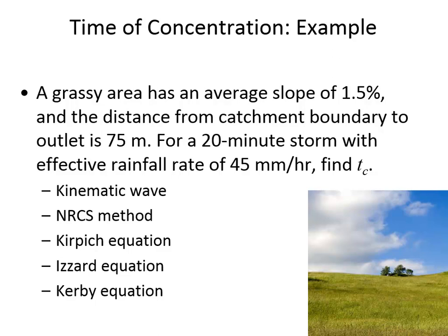And the problem with the Kirpich approach, of course, is that it doesn't take into account the rainfall intensity or really, in a very meaningful way, the roughness of the surface. And so it really underpredicted how long it was going to take according to the Kirpich method. Izzard, 38 minutes. Kirby, which is another one of these methods, 18 minutes.